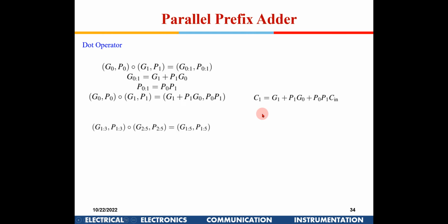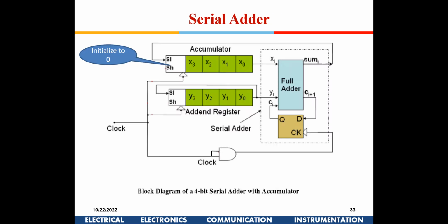But when we are talking about the gigahertz range, this clock is very high, right? So now if you see here, what is the element which decides the clock frequency in this particular circuit? What puts a restriction on the clock? How much delay you have to cater? The adder. Yeah, one bit adder, that's all. Correct? Just the 1-bit adder, so only that much delay you need to cater.